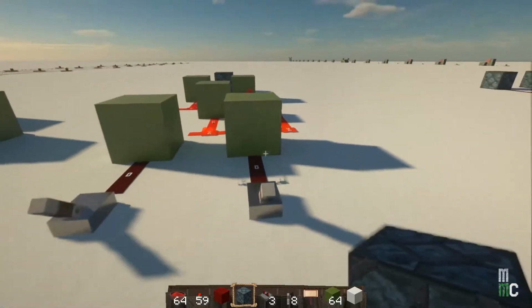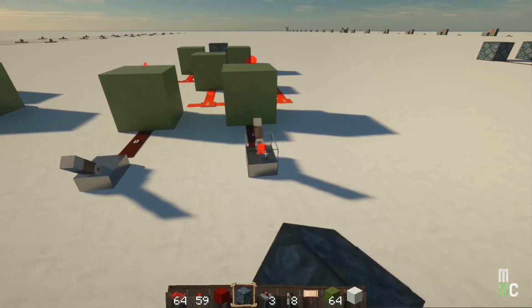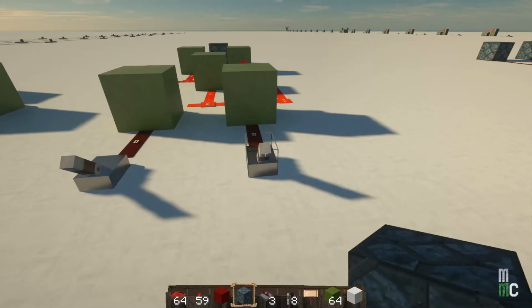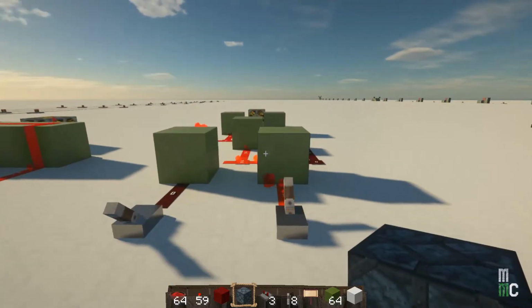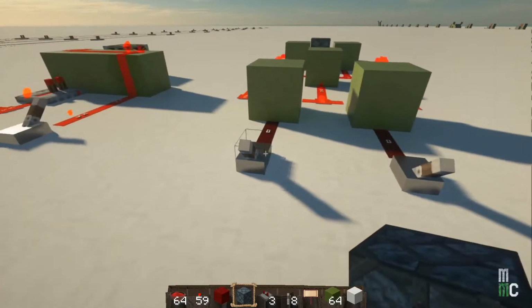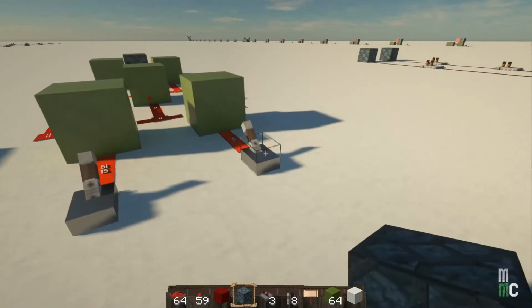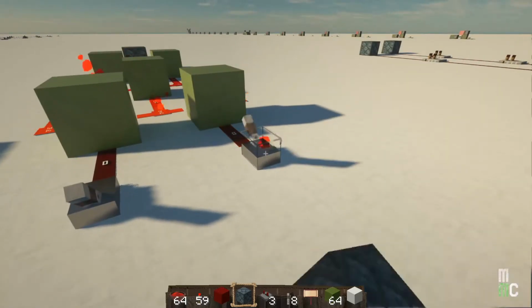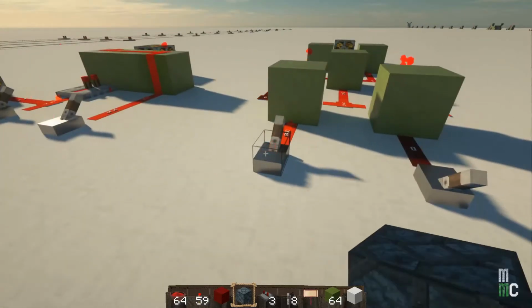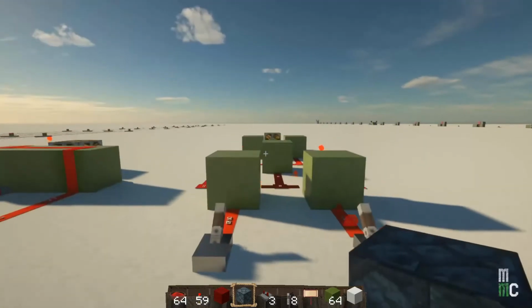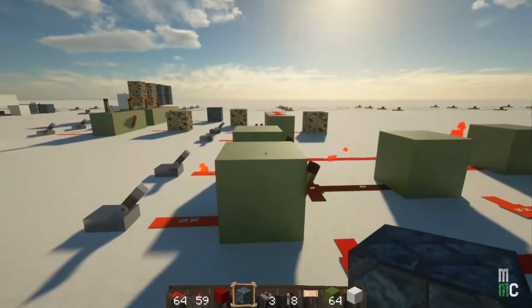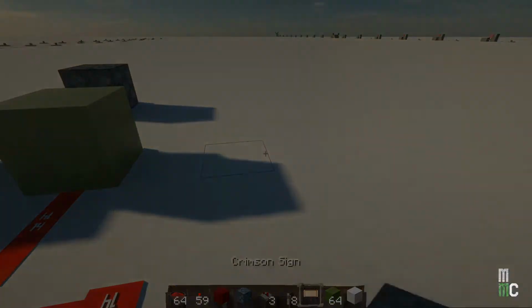In this case, when they're both off, the output is off. When I flip one, it comes on, or the other, but when they're both on, it goes off. So this is an exclusive OR gate. It means exclusively OR, not both, one or the other. Off, it's going to be on, and if they're both on, it goes off. That's an XOR gate. Once again, if you remember, this is basically an AND gate, as we build an AND gate over here, so this can be done differently.